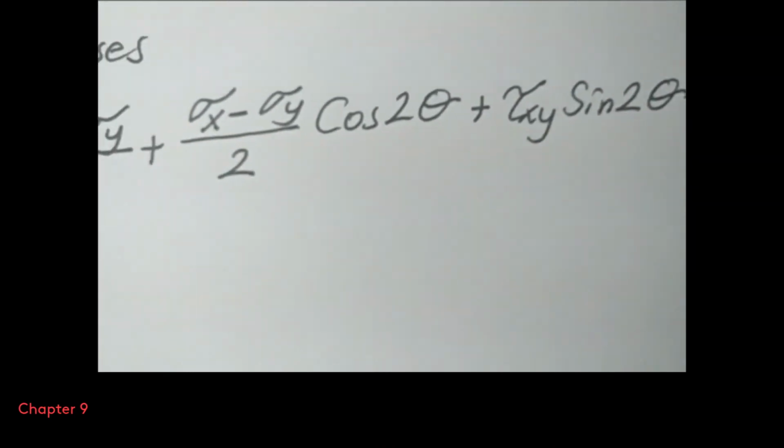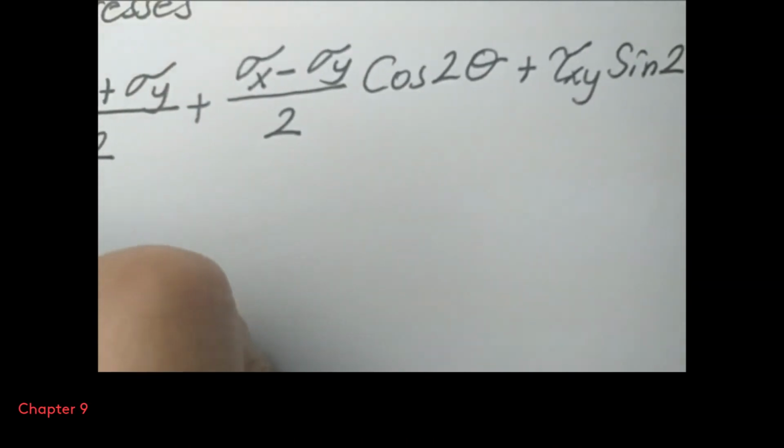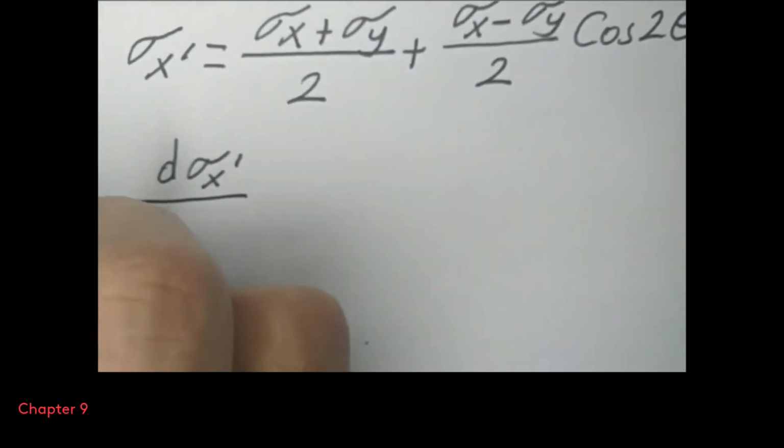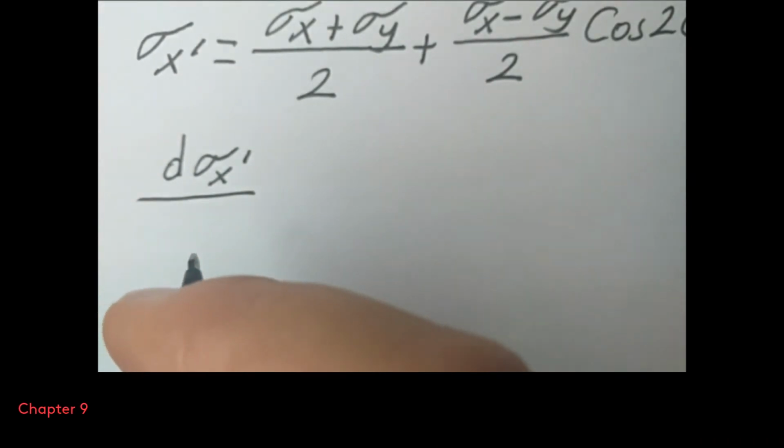What we need to do is we take the derivative of the stress value with respect to theta, and it has to be equal to 0.